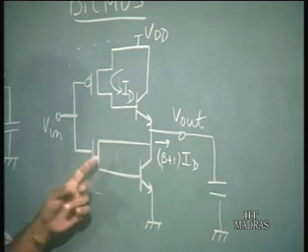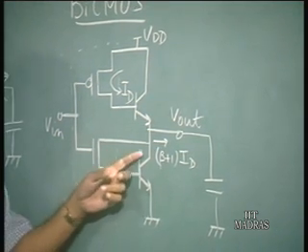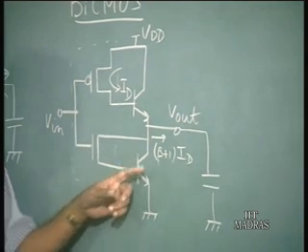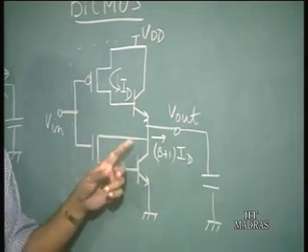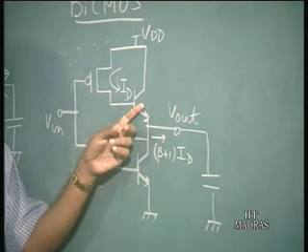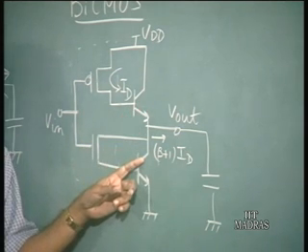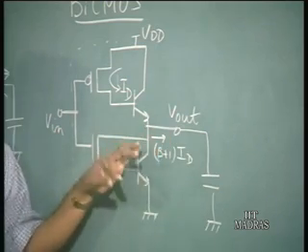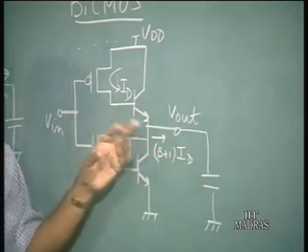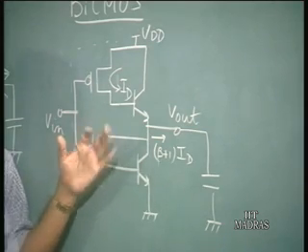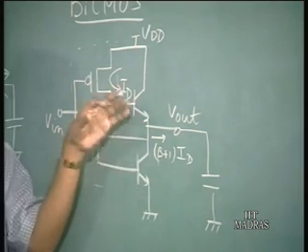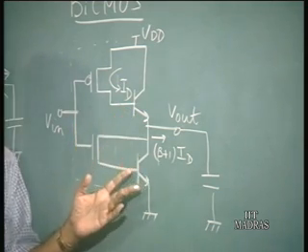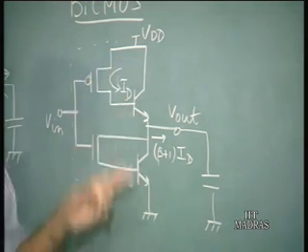On the other hand, since the NMOS is off, the base current of this lower bipolar transistor is 0. So, this lower bipolar transistor is off. So, it is not conducting. So, when the upper bipolar transistor is conducting, the lower bipolar transistor is not conducting. So, basically once this output capacitance is charged, there will be no current flowing, because although the upper transistor would be in a conducting state, the lower transistor is off, and so there would be no static current flowing in this logic gate.